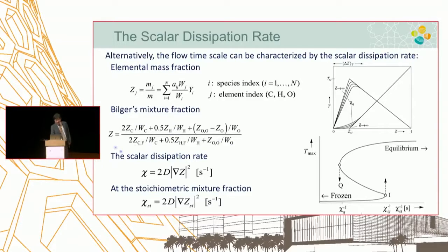So this is a kind of weighted average to accommodate those differential diffusion effects. But like I said, in large turbulent combustion, this effect is expected to vanish. There have been sophisticated refinements of the Flamelet theory to account for this Lewis number effect, but those are usually not commonly adopted in actual simulations.